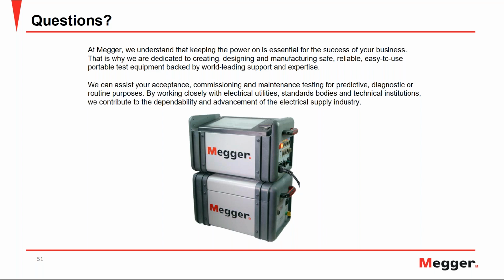But once again, anytime you see values improving by themselves or a negative power factor, we should investigate, and we should not put that back in service. The reason I say that is, let's say you clean the bushing and still the values are negative, that's an indication of internal surface leakage current, which you cannot avoid and which is not good for the bushings. So again, you need to investigate negative power factor values.